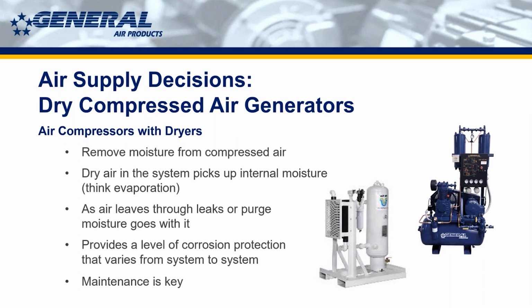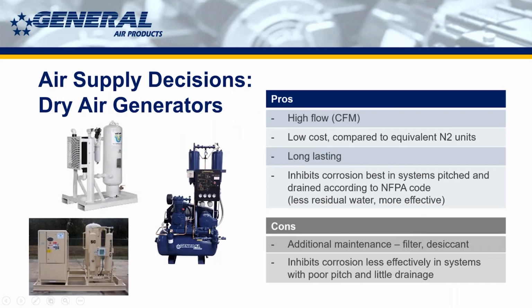You will not be preventing ice plugs, which is what it was designed for. Just like if you do not do maintenance on a nitrogen generator, you're going to soil the membrane. It'll get water or particulate in it, and that will cause it to not make 98% nitrogen. If you don't make 98% nitrogen, then you are not effectively inhibiting corrosion. And you don't have a very good dew point if you're using it in another capacity. So anyway, that's dry air in a nutshell.